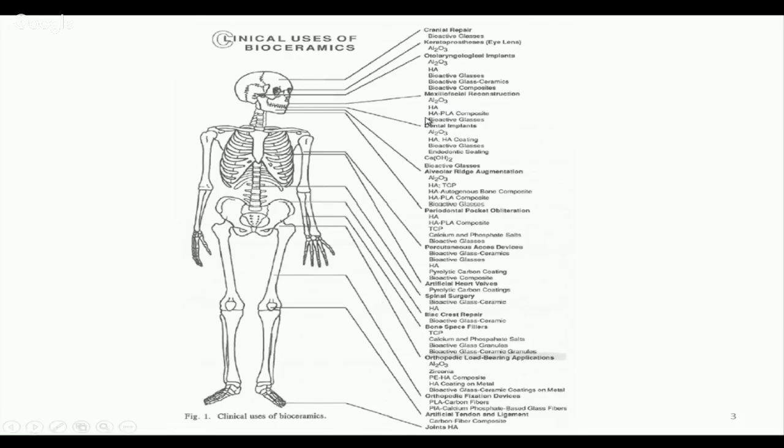Polylactic acid is a hydrophobic polymer, and a polylactic acid hydroxyapatite composite would be good for bioactive bone graft application. And as I said, alumina is used for maxillofacial reconstruction, where morphological fixation, the Hulbert concept, not the Larry Hench concept, is used. Because it is not for load bearing applications, tissue will just grow into the pores, and that is how it integrates with the tissues.